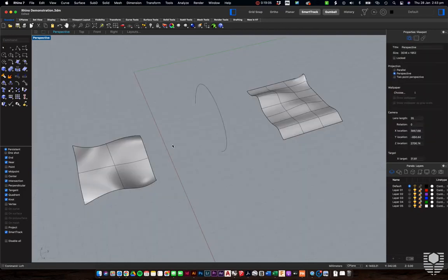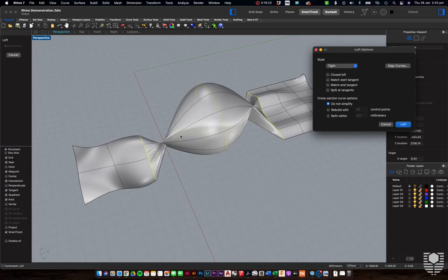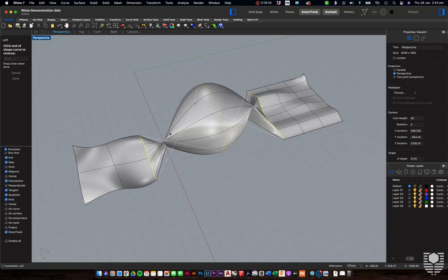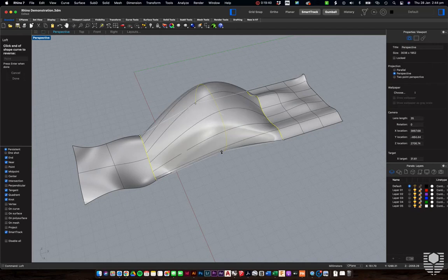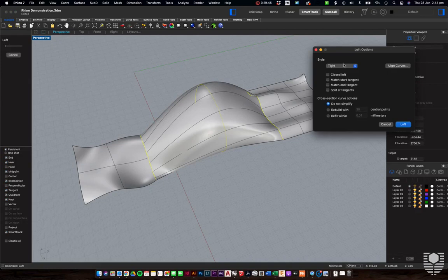All right, let's look at one final loft command. In this scenario, we want to connect this surface up into this new curve that we've added and then back into another different surface over the other side. So we hit Loft, click the curves that we're trying to connect in the direction we're trying to connect them, enter, and then we get hit with a problem here. So we can see that these surfaces are trying to intersect with themselves. If this does happen, just come up to here to align curves, and then we see that, yes, there is a crisscross going on. So we click the problem, which is this one here, to flip it back over, and we see it's now corrected it. Hit enter to finish aligning the curves, and now we can play around a little bit more.